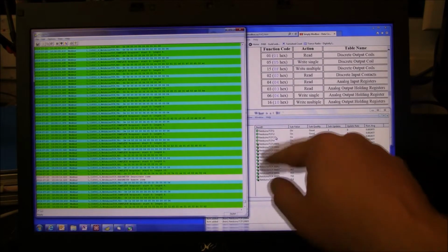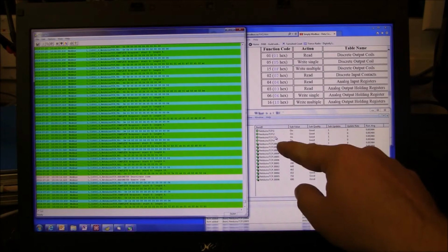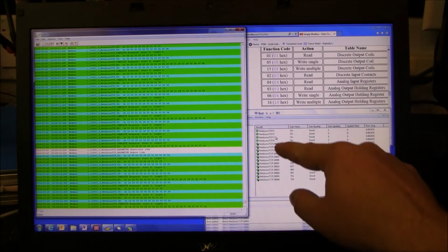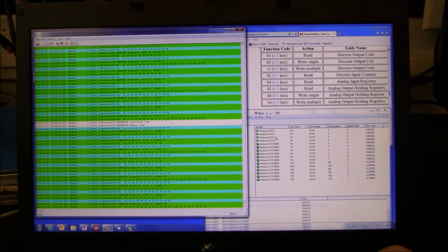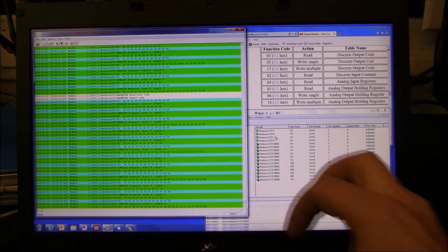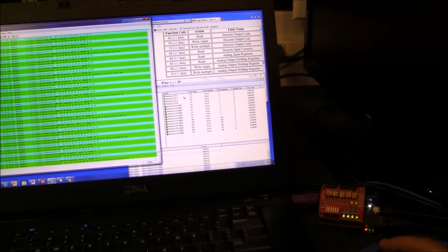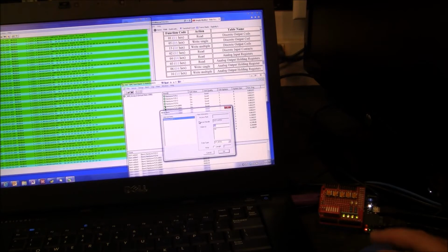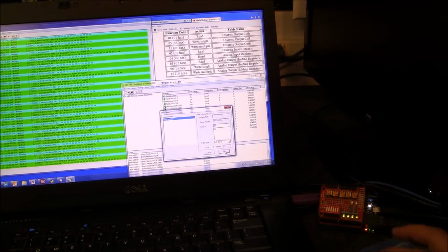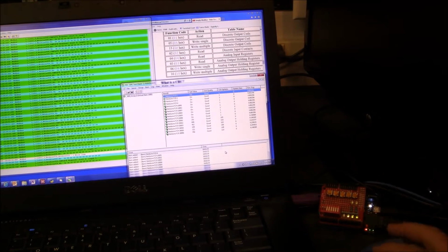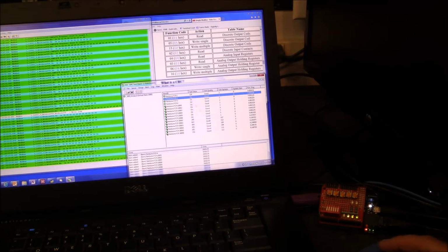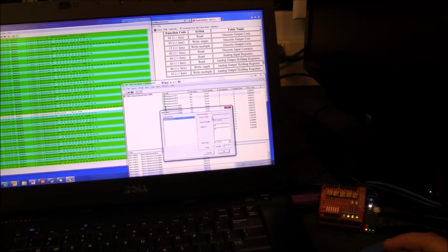So we have our coils. So Modbus, we're asking for registers 1 through 4. Those are the coils. Those are the things that we can write to. Netduino down here, I'm going to write to one of these real quick. I'm going to write a fault switch is off, and you'll see that number 1 just went off. Watch closely to number 2. Sync right, nope, sync right, off.